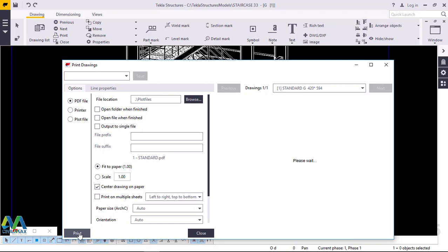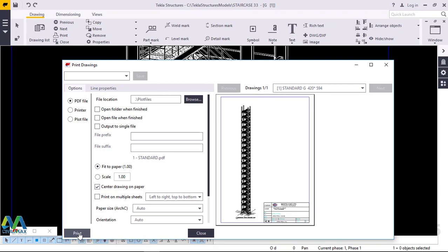If you're comfortable with the rest of the settings, which I'll take you through on how to set them up, let us have a preview of what we want to convert to PDF. There we are. We have a preview of the isometric view of the drawing that we generated from the model. So we have the option fit to the paper, and also use the scale. You can use a scale of 1 to 20. You can feed it here so that it can have the exact scale of the drawing.